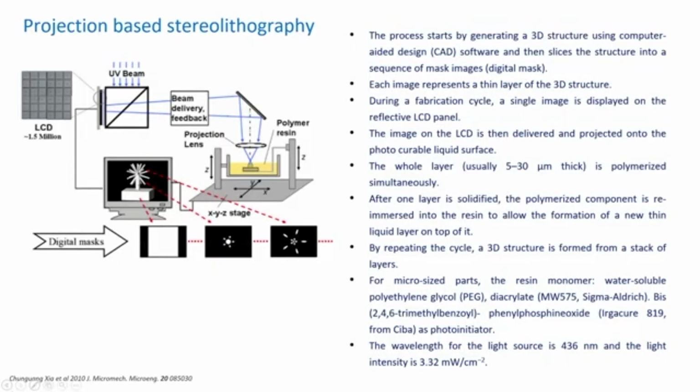So, there is another interesting technique in stereolithography, that is an integral process itself, and it is based upon projection. On your screen you can see this particular arrangement. We have the typical stages: the polymer resin bath, the focusing lens and the bending mirror. Now, instead of the dynamic pattern generator that we saw in our previous case, here we are using an LCD, that is liquid crystal display.